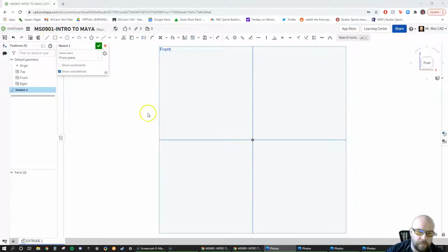or I could click L, which would also do it. But I'm going to go up and click my line, and I'm going to kind of just make that general shape. So I'm going to click here, I'm going to move up, I've let go of it, and don't worry about the number. We're just creating the shape, and we're going to put in dimensions afterwards that are going to change the size of the shape. The key is drawing the shape proportionately or pretty close to what it looks like. So I don't need to go up to 2.5, and I'll show you that. I'll go to an extreme here. We're just going to go up to like 1, somewhere around there. Whatever you want, doesn't matter. You could go up to 20, and we can still make it work.